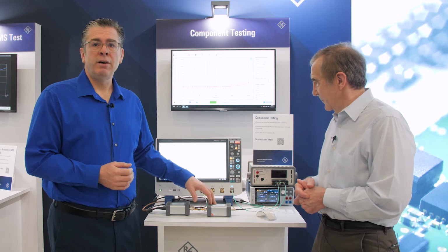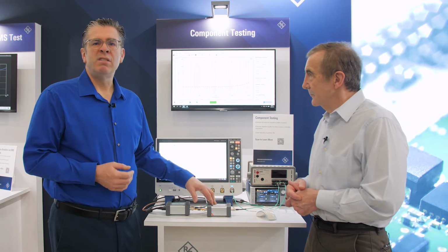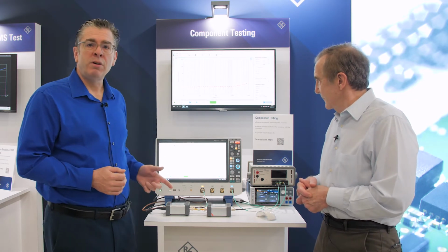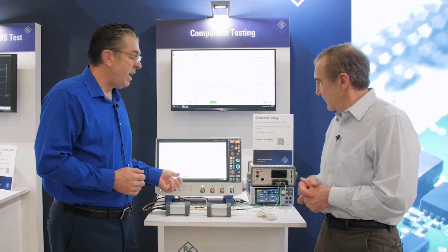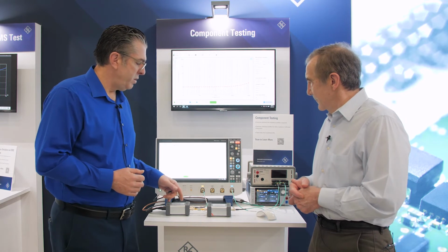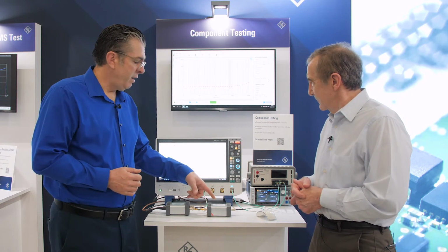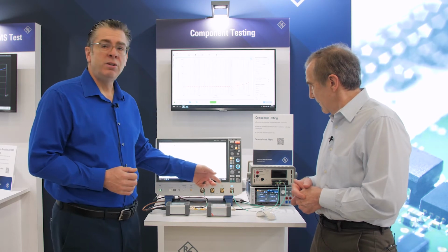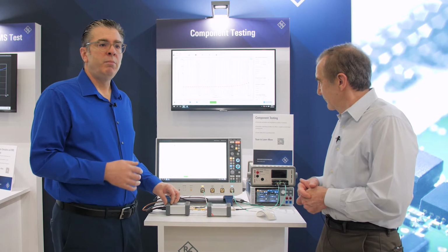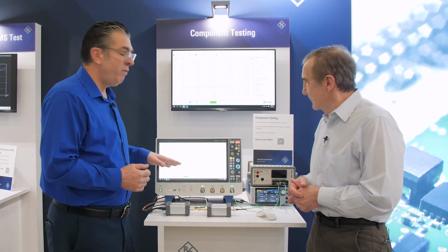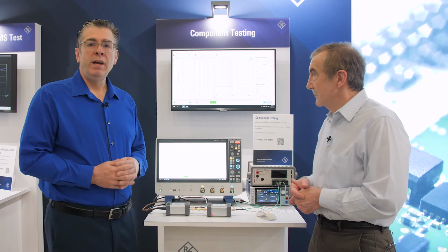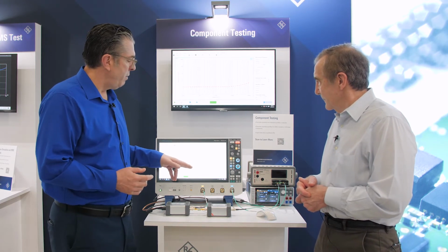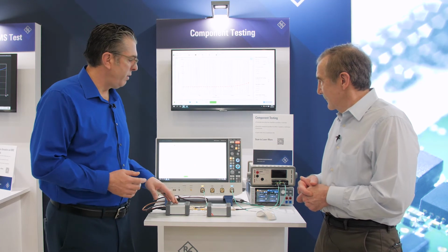You have a ground isolator that gives you a flat frequency response out to, say, 6 gigahertz. And you have an active splitter, which takes the generator off the back of our scope and applies a sine wave into the splitter, which is then split between channel 1 and through the DUT and into this isolator and into channel 4. So it plots the math over frequency to give you an impedance curve. In this case, we're looking at a 1 milliohm resistor, and you can see you're getting this 1 milliohm measurement until it starts to drift up.